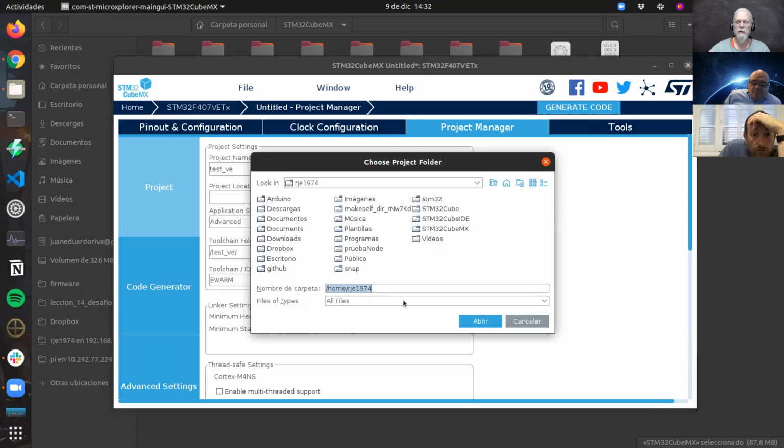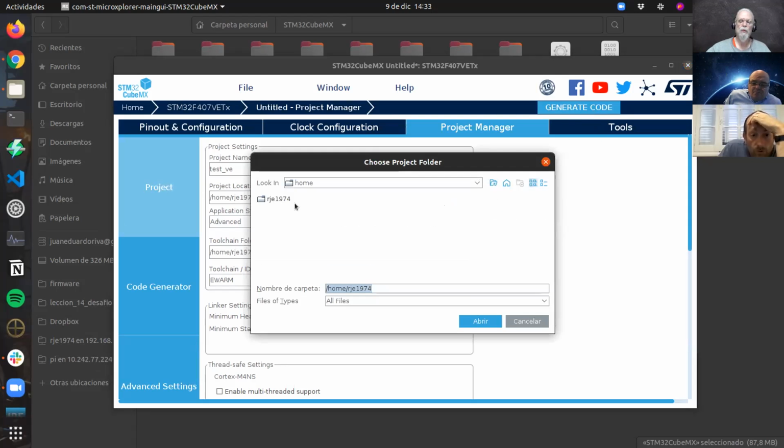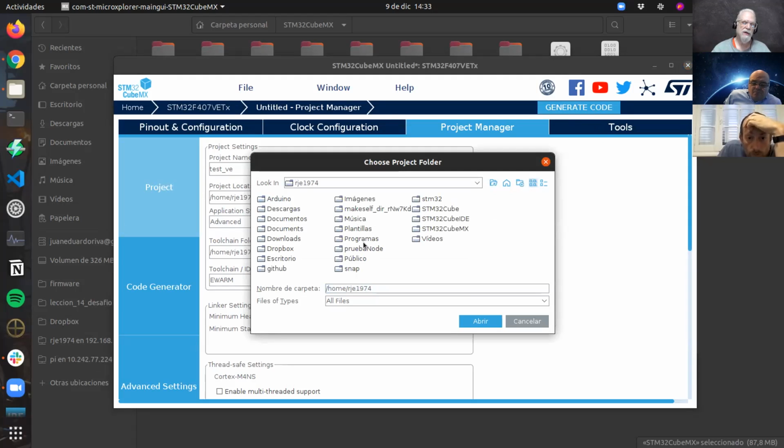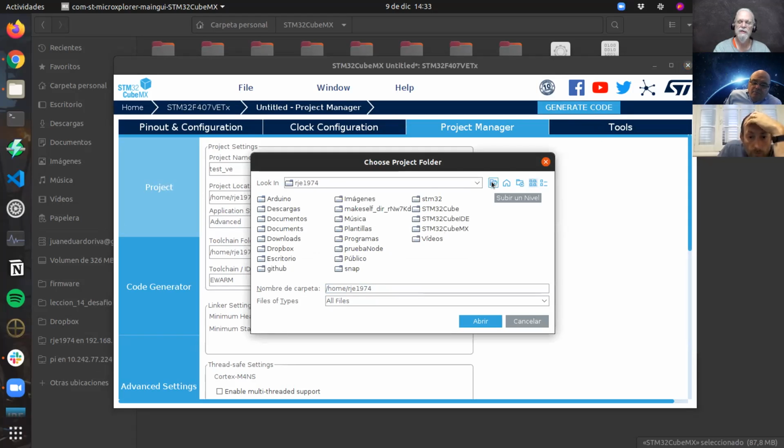The point is, at this point it will generate a short little piece of C code based on whatever blank chip you just loaded in. Once it's saved, you can go back and do the same process with the VG chip. Then you're going to get two projects that look identical, except one place will list the processor number, and somewhere else it'll say that processor has 512K of memory versus 1 megabyte of memory.